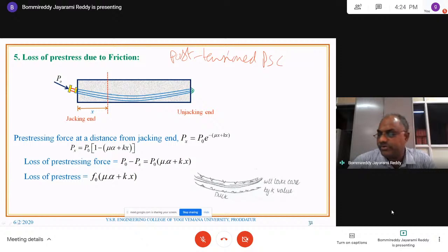What we normally do is, this is a structural member, which is cast leaving the shape of the duct throughout. At the time of casting itself, some pipes will be kept in this particular direction. When pipes are kept in this direction, they will form a clear-cut duct.